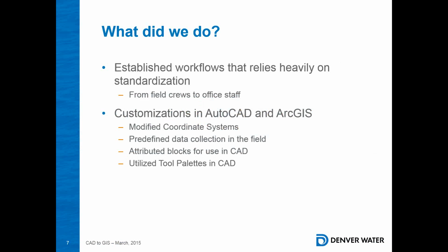But for the FDO, what we're talking about here is allowing the GIS into CAD for the overlay for engineering to use, and then also that posting back. So every time we talk about FDO connection, it's a little bit of a misnomer, and Sandy will always tell you she wants to change that name, because one of the things we are using is definitely the feature data object technology inside of Autodesk applications in order to gain GIS data and overlay it inside my engineering. But at the same time, we are also using the import-export, which is technically not FDO. It's a direct translation. So we'll figure out a better name for that.